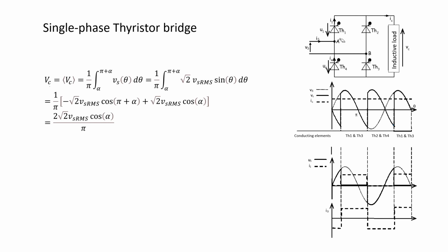And then if we want these to be off, because we cannot control them to be off, we just send the signal to turn on thyristor 4 and thyristor 2. So when these two are on, these two are automatically off, because the circuit will force these two to be off, right? So that's why here we can have a waveform like this.